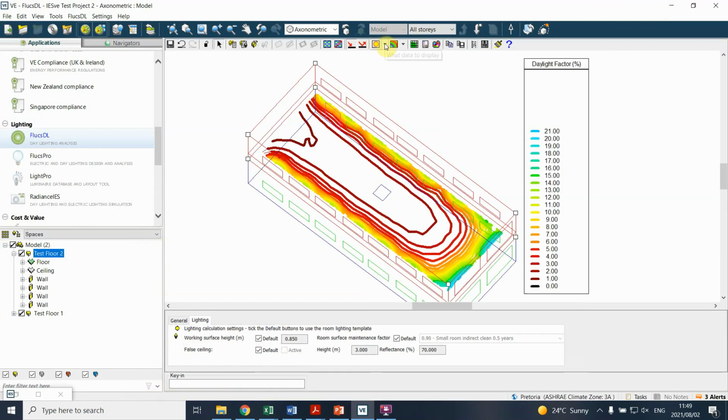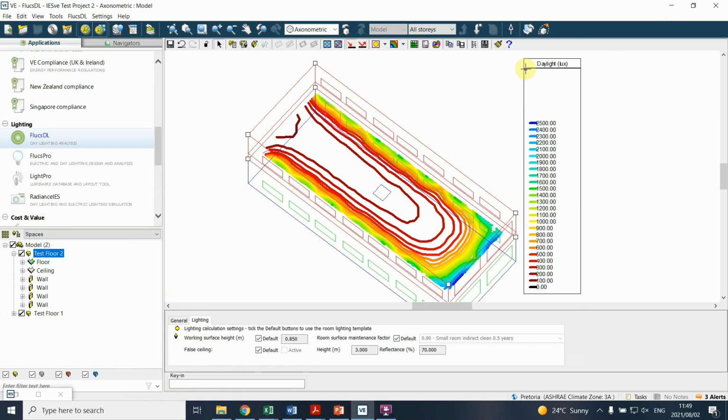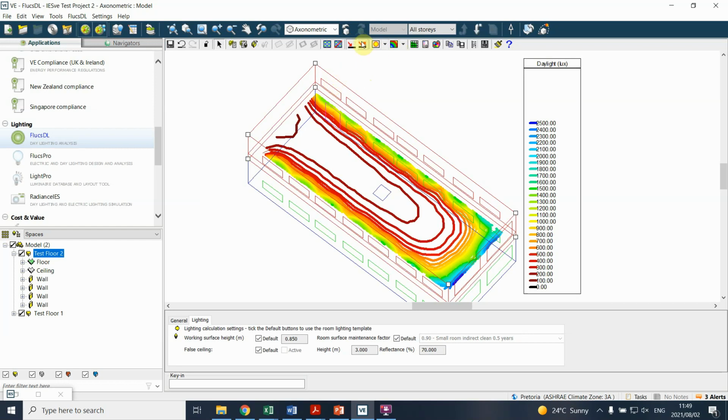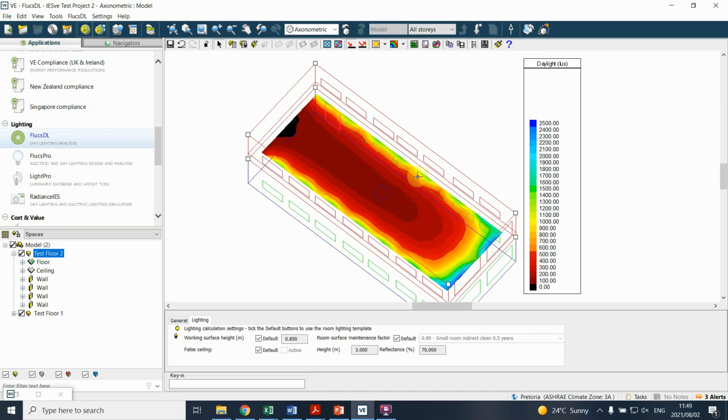And if you adjust this and you say, well, I don't want to look at daylight factor, I just would like to look at daylighting, then if I choose daylighting under this little section, you'll remember to choose the space again. I'll see that my index now changes, and I can actually now assess it. So I can see, okay, wait a minute, this is where the lux levels are assessed for the various spaces, and we can again use the same method.